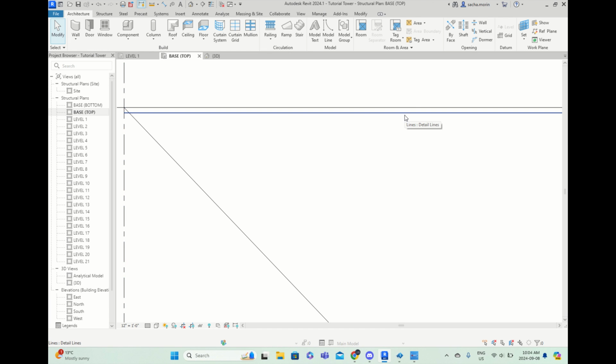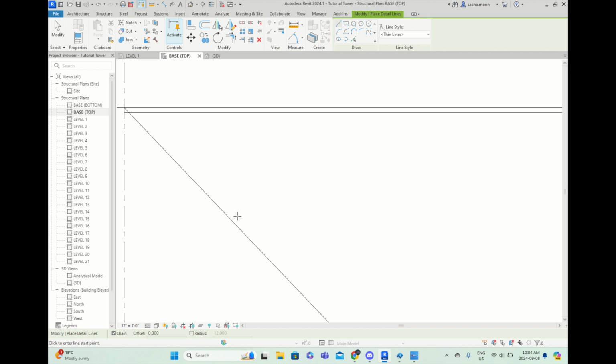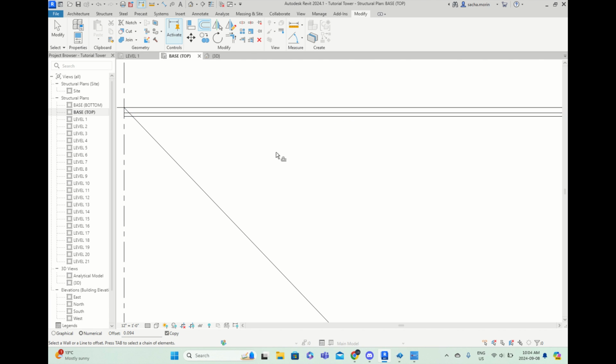So then to make our column, we have to make another offset to go halfway through that column, right? Because it'll be defined by the center. So let's use that offset tool again. OF, we will offset by 3/32 of an inch, which is half of 3/16. I'll use the offset tool here. Boom, 3/32. And we'll do that. Bang. All right. So that is the line where half of our column will be.